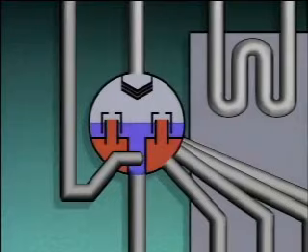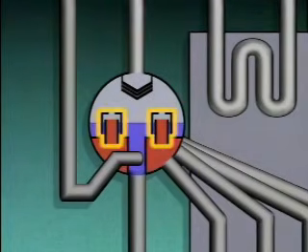Superheated steam is desirable because higher temperature steam can do more work in the turbine. Additional work from the same amount of steam production makes for a more efficient generating unit. The steam in the drum of a typical drum-type boiler is at its saturation temperature. As the steam leaves this drum, it passes through moisture separators and dryers, which remove water from the steam and thus prepare the steam for superheating.